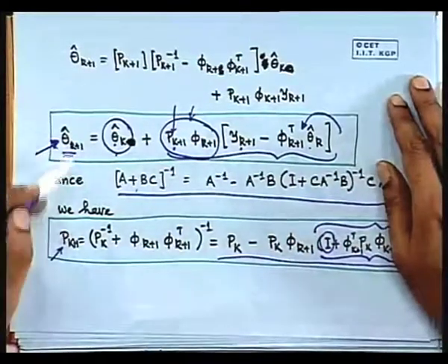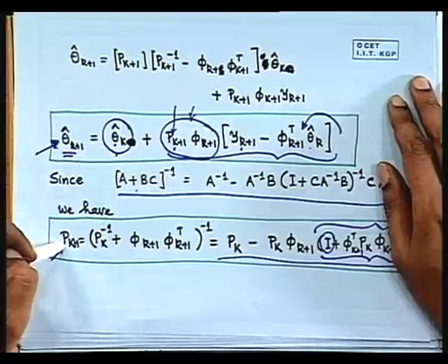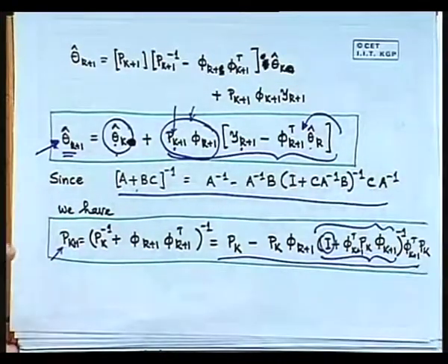So this is my recursive least square estimator. What have I done? I have first got a set of measurements. I proposed a model form. I simply fitted it in the least square manner, and then I found a way of updating my least square solution if I get another measurement. So I can do it recursively. Every time I get a new measurement, I can just update this equation once, and that will give you the new least square solution.